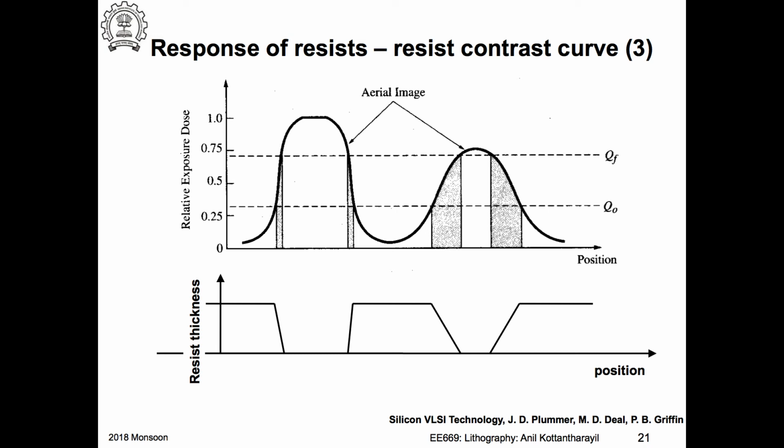Edges are not vertical, right? So even in a line of sight deposition, I would get some film deposition on the side walls. Here it would be worse. Okay, so this is a very important consideration, and